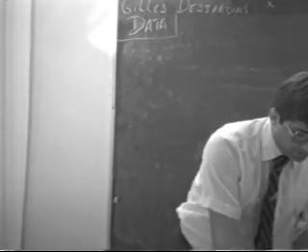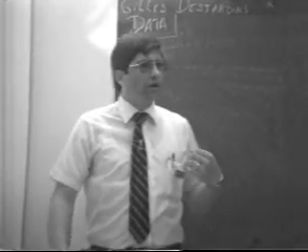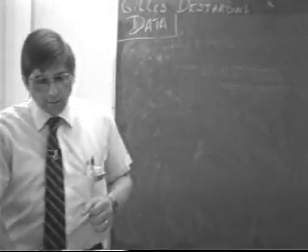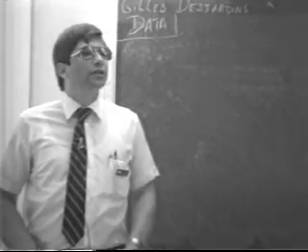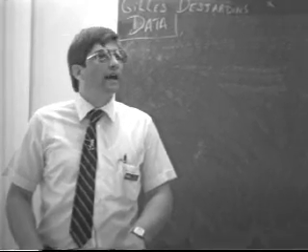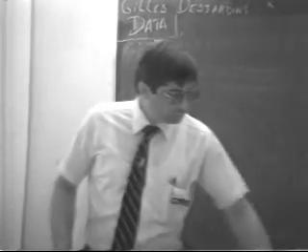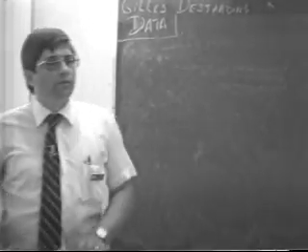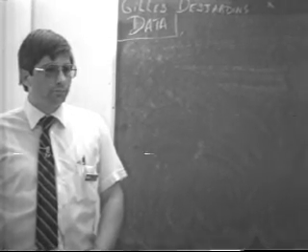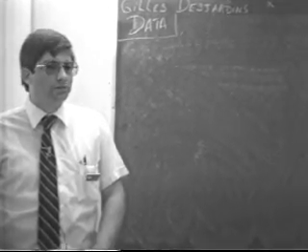So that takes care of the CSS card. This morning and just now we finished talking about 2 cards, the CSS and the RSS. And these cards are considered to be the digital portion of the sound system. So our maximum frequency output will be 2 kilohertz. It is possible to test these cards through the DAC bus test set and manual. You can also disable the card, put it on test mode, and insert your own signals if you wish.